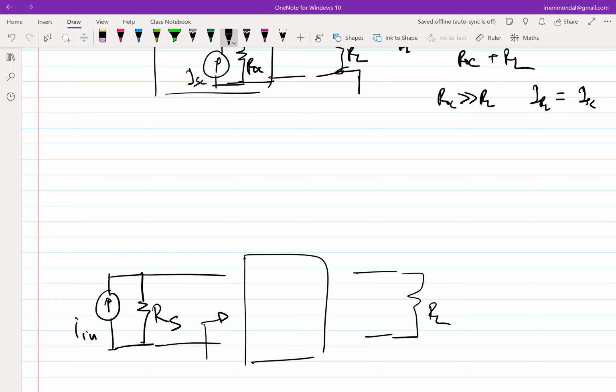Given that you know how a transistor works and you know what the impedances of a transistor are, can you tell me what am I looking for here in the incremental sense? I will put the full-blown transistor later. In the incremental sense, which terminal of the transistor am I looking at if I want a low resistance? Source, right? Looking into the source is 1 over GM.